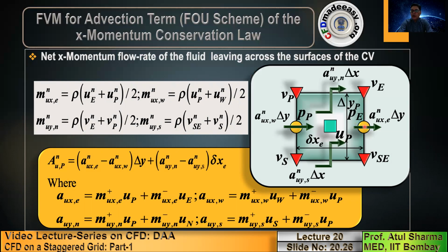Now you don't have a green square here. So to calculate u at this point, which is ue for this control volume, this will be given as u capital E plus u capital P divided by 2. This I presented for a uniform grid. For a non-uniform Cartesian grid, instead of dividing by 2, it will consist of the non-uniform width of the control volume.